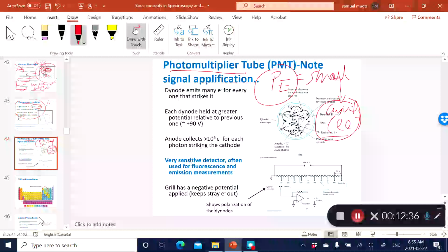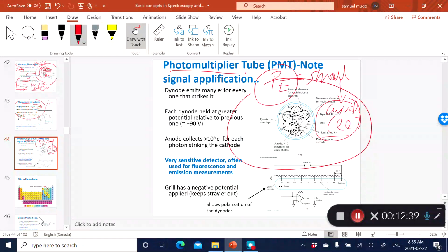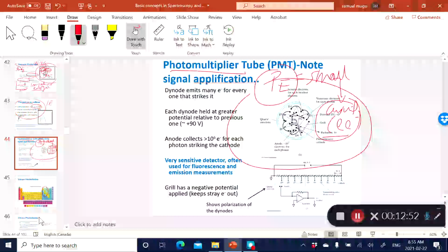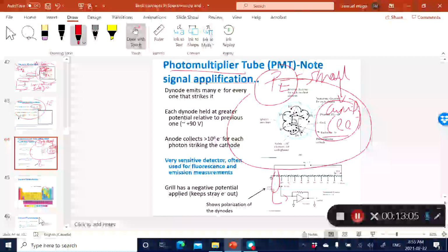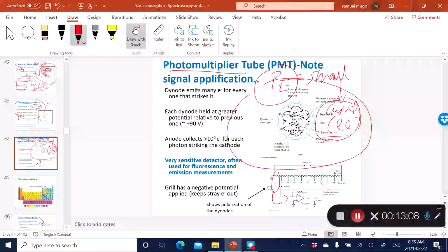Let me try to explain how it works, based on this figure here. Now, one vacuum phototube, you're often going to see some experts calling it a diode, okay? The reason they sometimes call it a diode is that it's connected to a power supply, often a DC power supply of a certain polarity. All right. So D refers to the vacuum phototube, which we already talked about, which is essentially just a cathode that is coated with a photoemissive material.